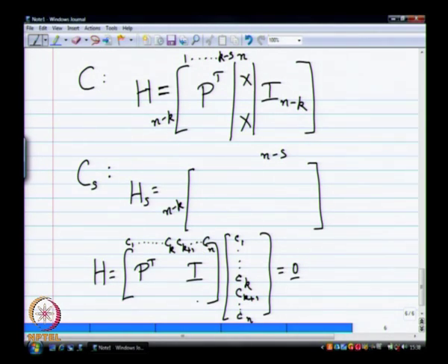So I can associate each of these bits with the columns of the parity check matrix. Okay, if I have a valid code word, what should happen? These columns will be multiplied by those bits on top and I have to add them up, I should get 0. Okay, remember this is my message part. So once I fill in my message part, how will I compute my parity part? The equation directly gives you the answer.